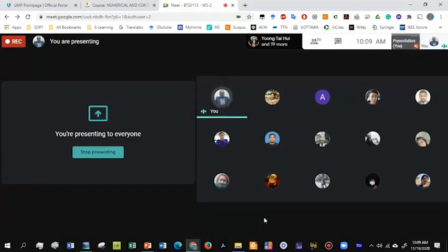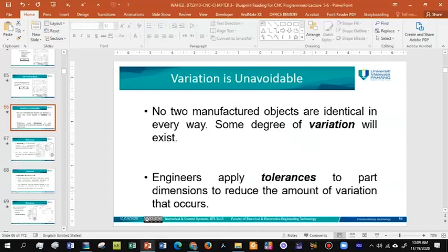They call it the tolerance, and usually they define this tolerance in the engineering drawings, and you can see in the examples that we had in the previous chapter 3, in the different drawings, there are some values we call the tolerance, which define what margin of error is allowed in this product, in this dimension. It's not about the total product. Sometimes this tolerance needs to be defined for each dimension, for example, the height, the width, the length, and the diameter, and so on. Each dimension has its own tolerance.